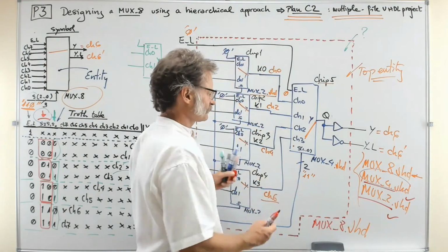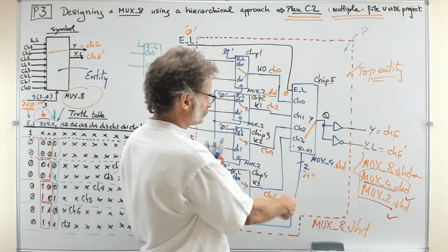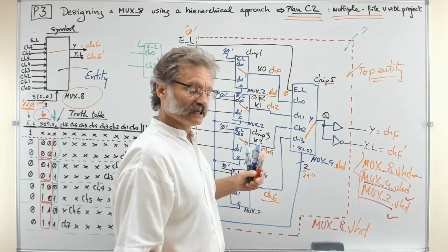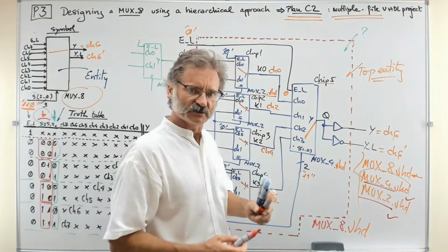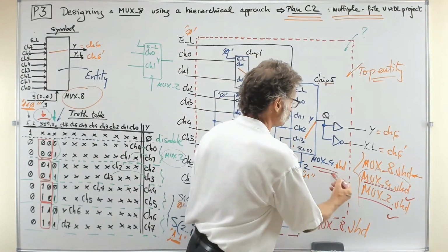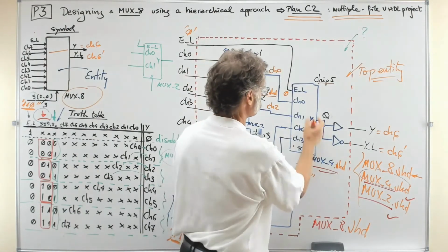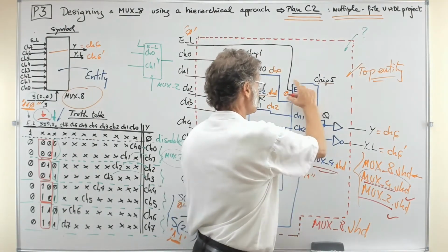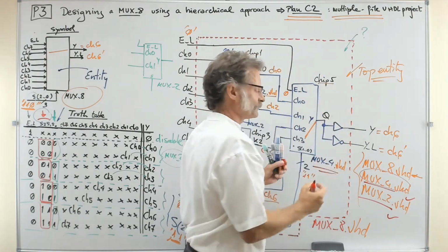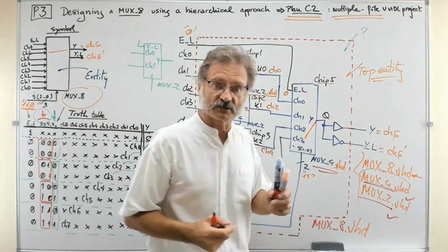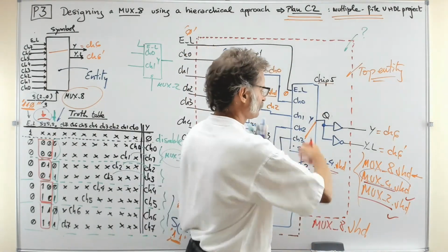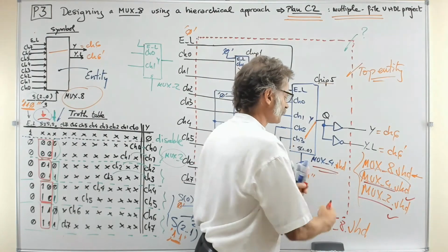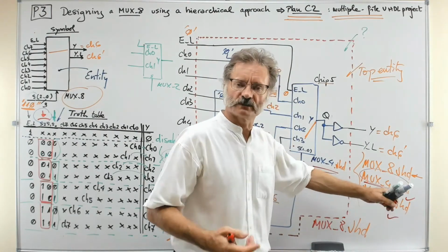So in the end, you have MUX2s in this top entity and MUX4, but perhaps you also have that internally, the MUX4, when you go to Control C, to the child sheet of this chip 5, if you go inside this chip, perhaps you may have inside another similar plan where the MUX4 is invented using MUX2 and whatever else.